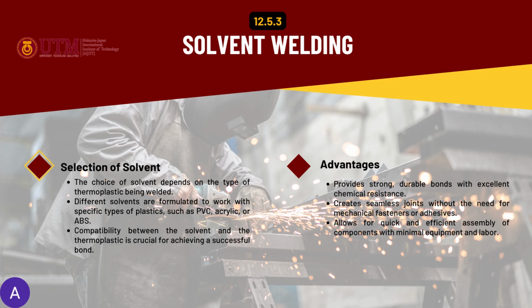Then the advantages of solvent welding. The first one is it provides strong, durable bonds with excellent chemical resistance, creates seamless joints without the need for mechanical fasteners or adhesives, and allows for quick and efficient assembly of components with minimal equipment and labor.